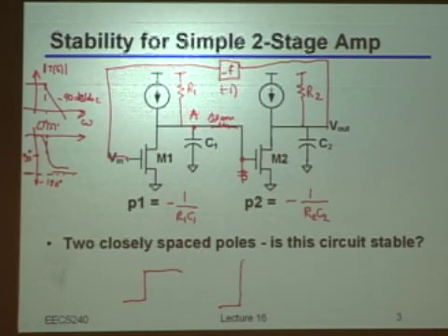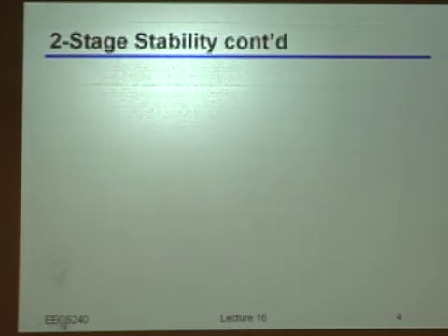And it could ring before really settling, and I could have even a bigger oscillation there. So the settling will be pretty slow. I will get the value that I want after a long time. So I might not be happy at all about an amplifier like that, also because of what we have already seen, like the settling time and the settling issues. So let's go and review a little bit how to make it stable. The point is how to recover the phase margin that we want.